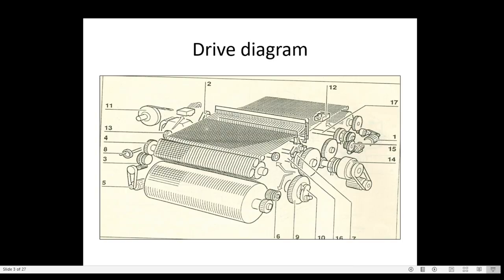Eighth, hand wheel is there. Here is the hand wheel to move the machine in slow motion forward and backward when the clutch is disengaged. Ninth is tape drive wheel. We can see here the tape drive wheel. From this hand wheel, tape drive wheel, the drive is going to the tape. By hand we can rotate front side and back side.